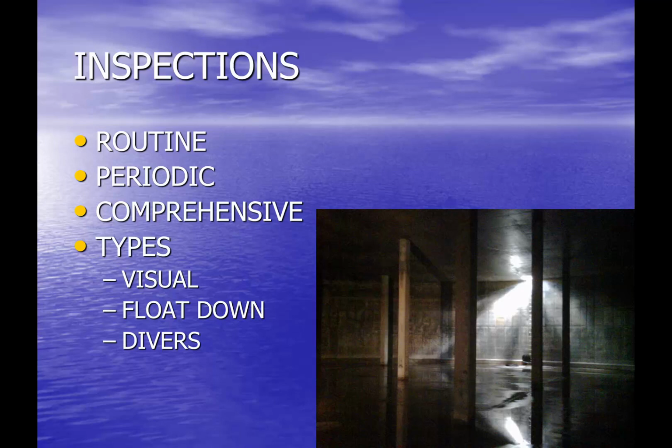And I'm a big fan of the dive inspections. We do these every 2 years on our tanks. We do it every year for our big reservoir. And the divers can get in there and do videotape, which we do on our big reservoir. They can take photographs, which we do on our tanks. They do damage estimates. There's a significant amount of underwater repairs that can be made.